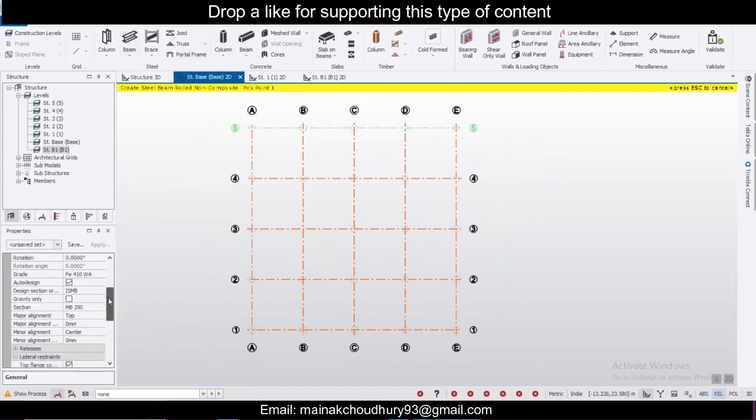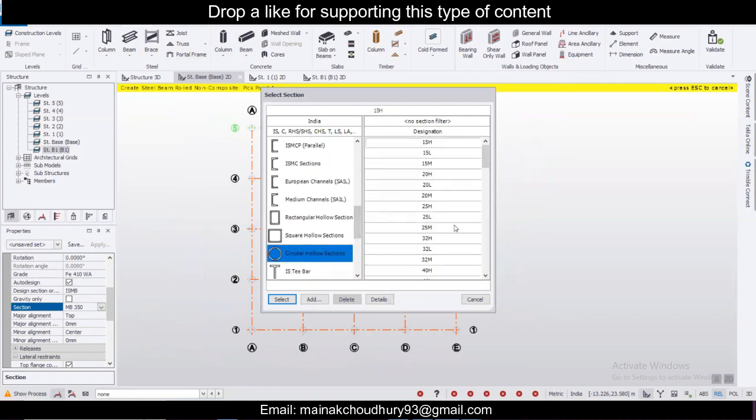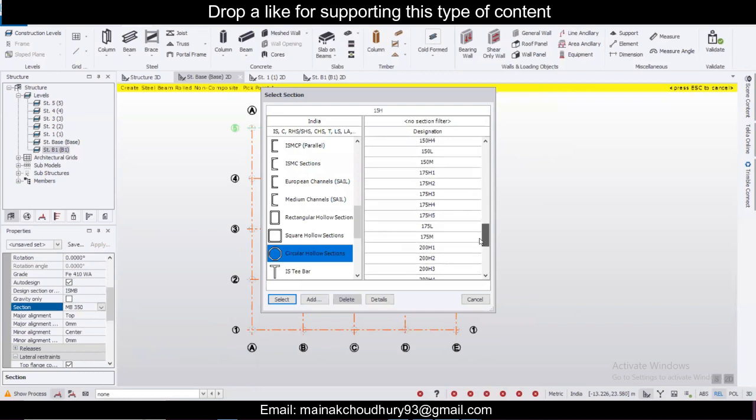So for the beams also, you can select any section which you want. Not gravity only, unselect this. Any section which you want, and in this section we'll go with our circular section as well. So circular section, and let's go with 200 H4. Okay, and go to select.